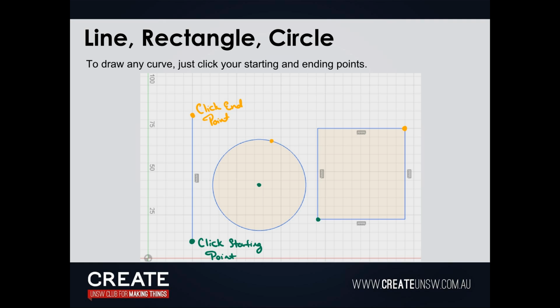So if I want to move this, double click that, hit M. M is the shortcut for move. There's different ways of moving it. So first you want to select your geometry. Now you can move it up. You can rotate it. There's no point in rotating a circle, obviously. Once you're satisfied with that, just hit OK, and you're good. Now you stop the sketch, and there's a circle. Okay, just delete that.